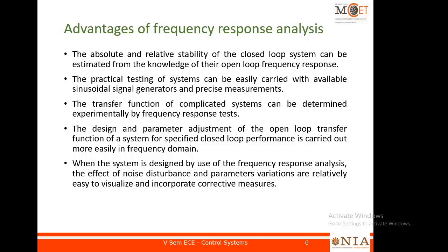If you want a closed loop system to perform in a certain manner, then you can adjust the parameters of the open loop transfer function easily if you work in the frequency domain. If you have designed a system and obtained its frequency response, and you find that there is some noise, then you go back to the system and make some parameter changes so that you reduce the noise.